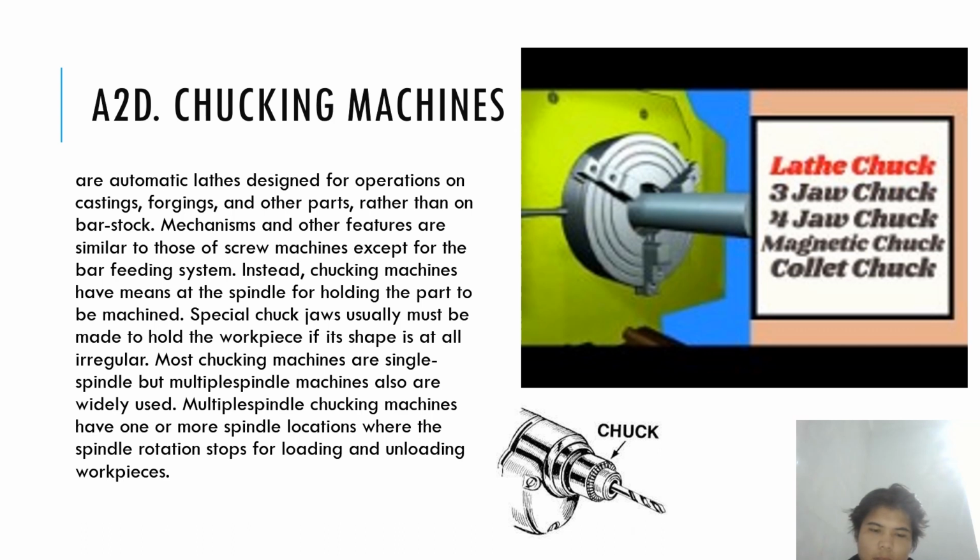It holds the workpiece in between the jaws of the chuck. When the chuck key is turned, all the jaws will move an equal distance at the same time. The work can be centered automatically and quickly.